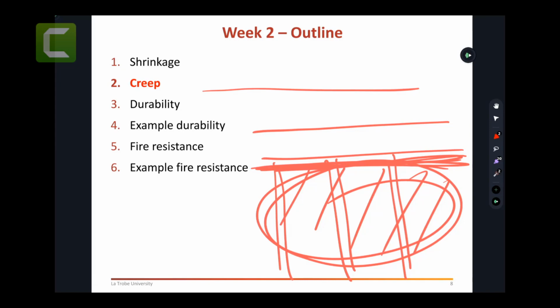When you strip it away, it will get impacted by the first load a concrete slab or beam or element can experience, which is the dead load. Usually it's heavy load, and that's where the slab will experience a bit high creep strain, eventually high deflection.